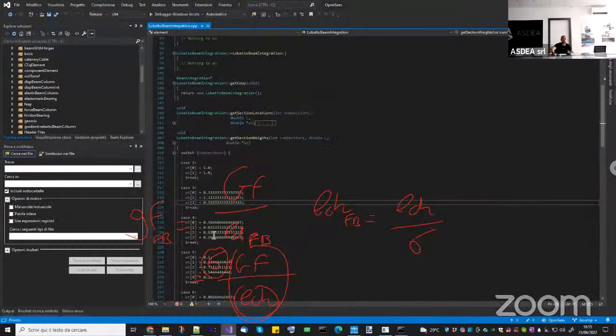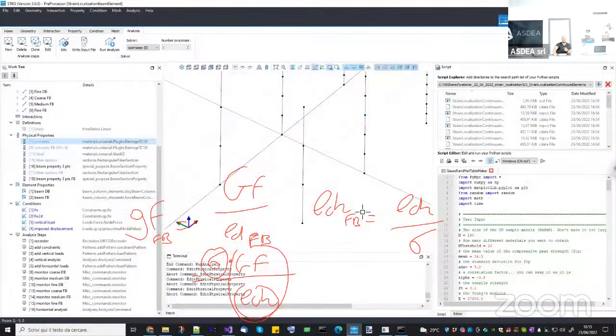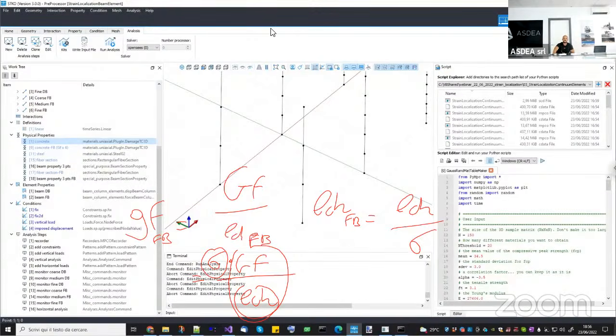Because in 5 integration points, for example, it is already 1/6, but this one has a sum of 2, so it should be divided once again. So it should be 1/12. So if I have 5 integration points, I have to increase the fracture energy 12 times. So is it clear? I know it's a little bit complicated, but okay, perfect. This kind of problem is only for force-based elements. Any other element which is displacement-based, you can assume that the automatic regularization is fine.